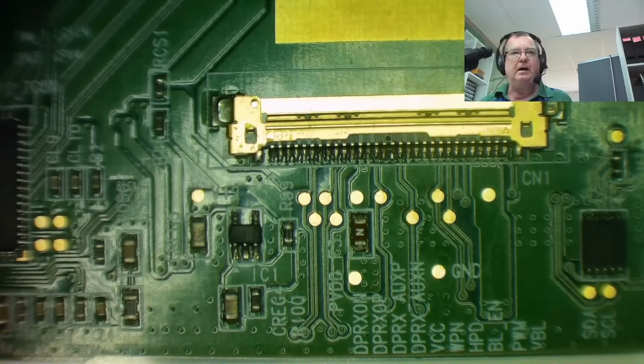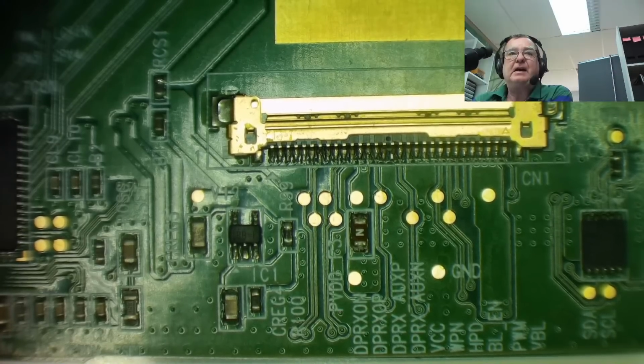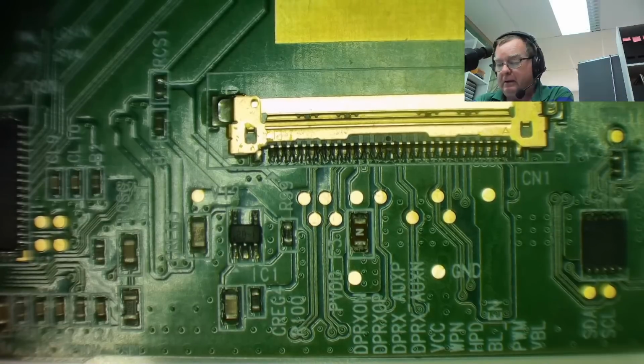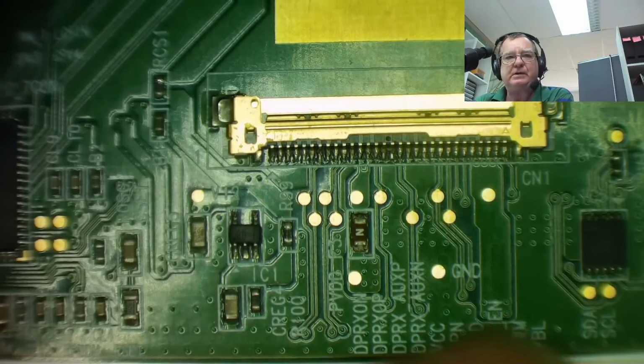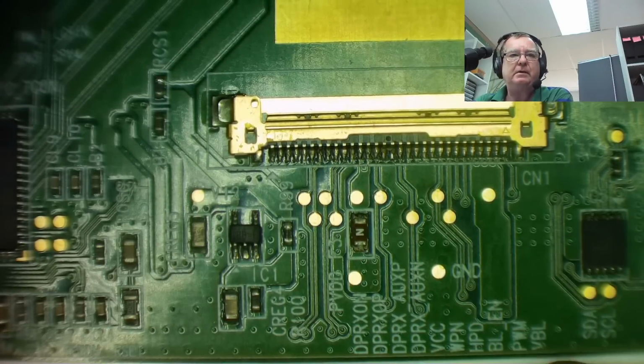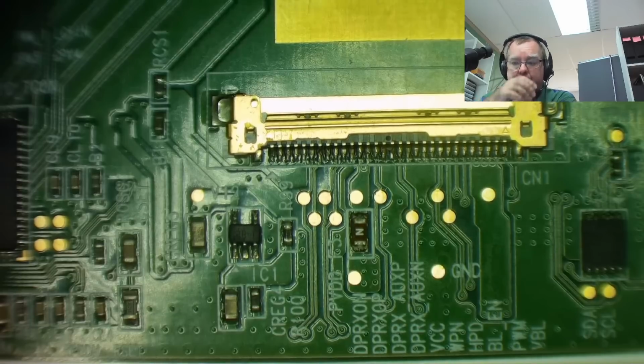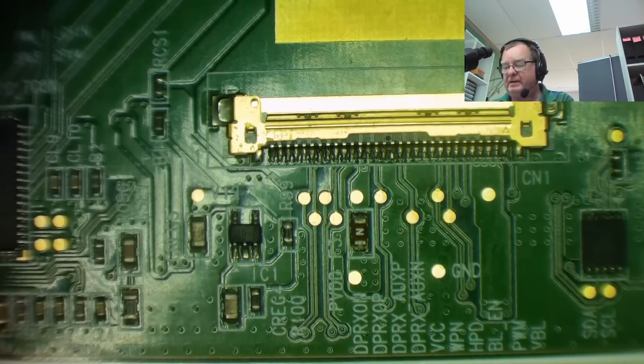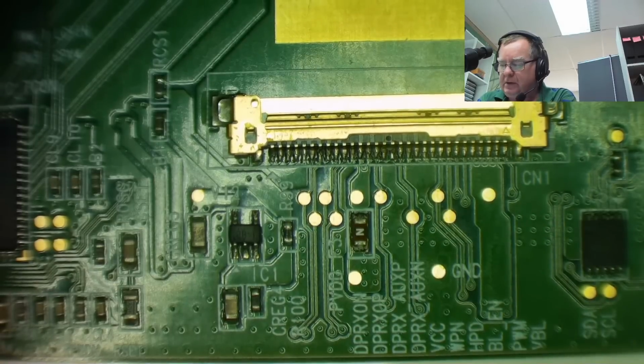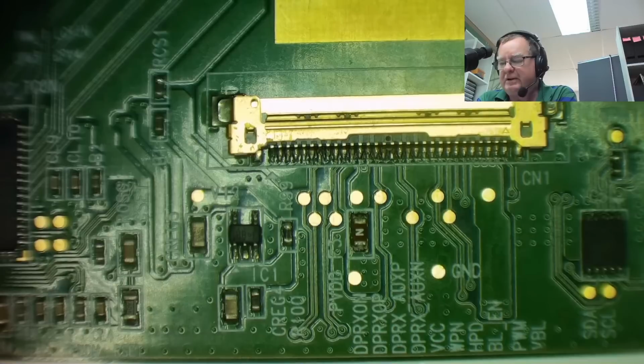Since yesterday, I went and asked on this Bad Caps forum, because they have a lot of laptop guys on there. I said I don't really fix laptops much, so I don't know everything there is to know about these, quite truthfully. So I asked about the problem, but I was more interested in what these signals are, these DPRX, ON, OP and so on, and asked if there was a pin out for the LVDS connector. This guy, Pierre, came back to me. He said, Rich, that isn't an LVDS, that's an eDP connector, which supersedes LVDS.